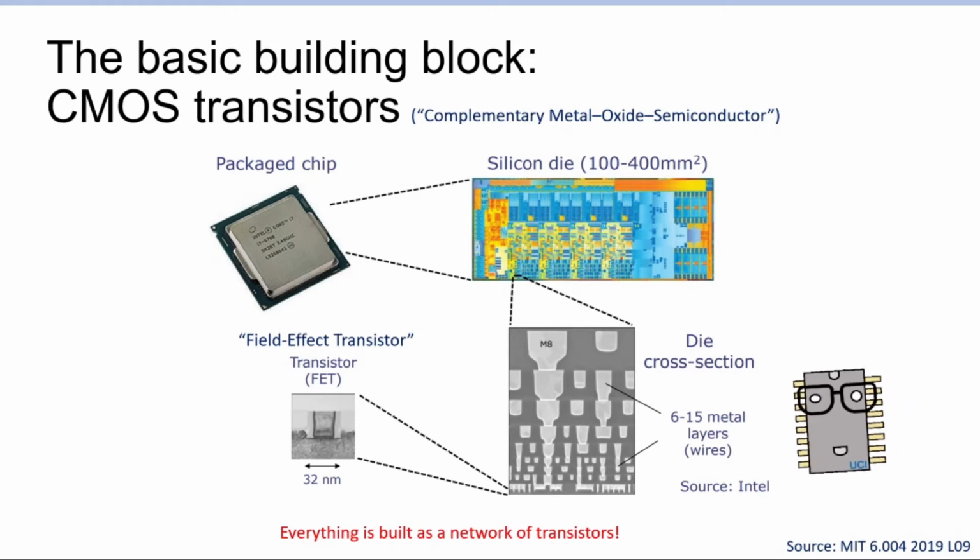So if you create a logical representation of a digital circuit which connects transistors together, for example, if there are overlapping wires, they would have to go into different layers of these metal layers. And there is absolutely a limitation on how many metal layers you can put using current technologies. So if a design has a ridiculous number of overlapping wires, sometimes it's not readily mappable. So there's a lot of research going into efficient mapping as well.